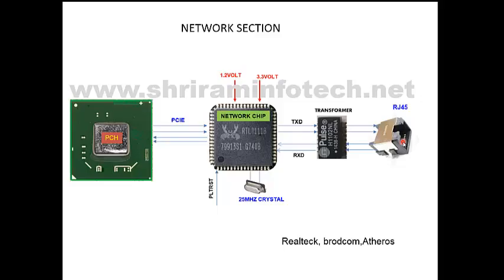Now if both are not working, and the connector is proper but the ping commands are not going, then you have to open the motherboard. Of course, before that you have to check the drivers also. The driver should be proper. Now if the driver is proper but still the network is not working, then open the laptop and locate the chip. This chip is normally made by Realtek, Broadcom or Atheros, either of these. So you have to locate this network chip. It is very easy to locate.